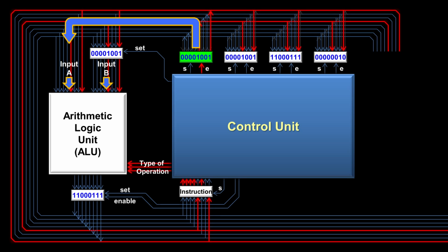So let's say the instruction we're processing is a compare instruction. With the compare instruction, we're not interested in the number that is output by the ALU. We only want to know how the 2 inputs compare to each other. For that, we use the flags that we talked about earlier. Each flag is just a wire that turns on or off depending upon whether or not a certain condition is true.